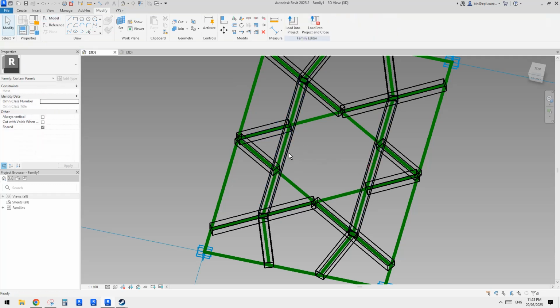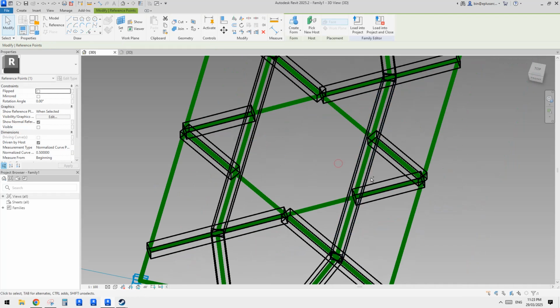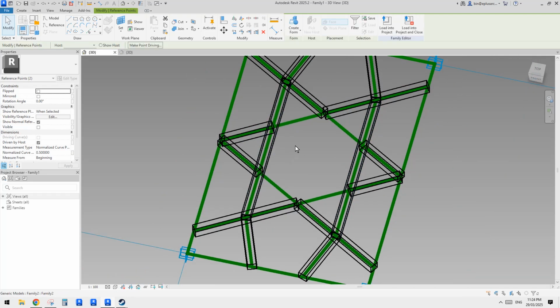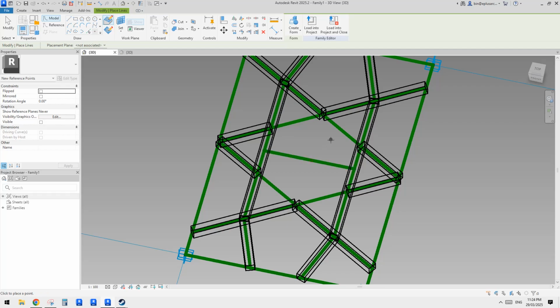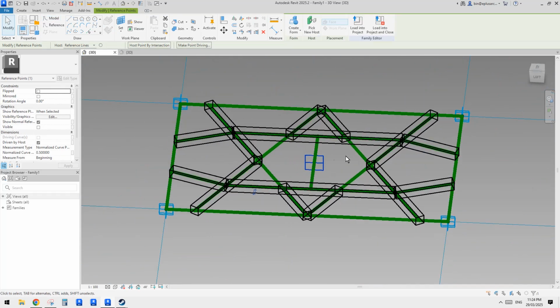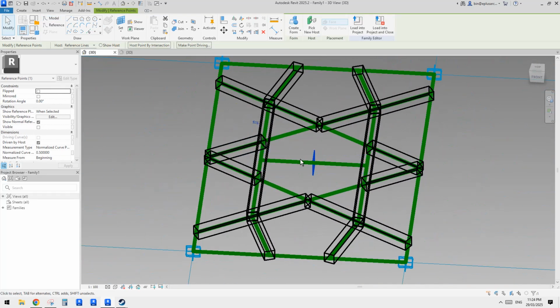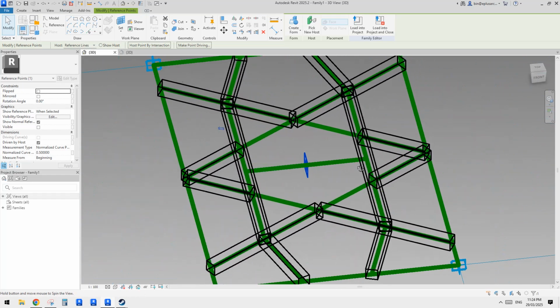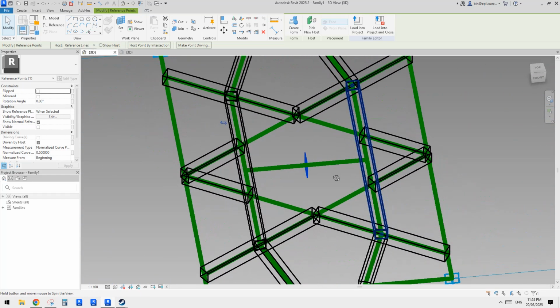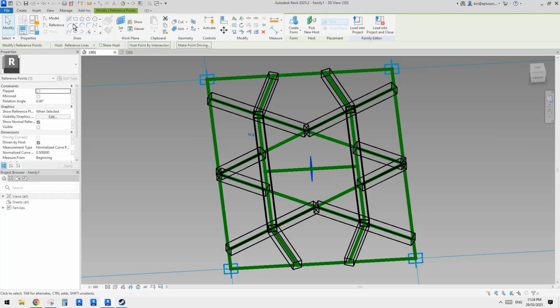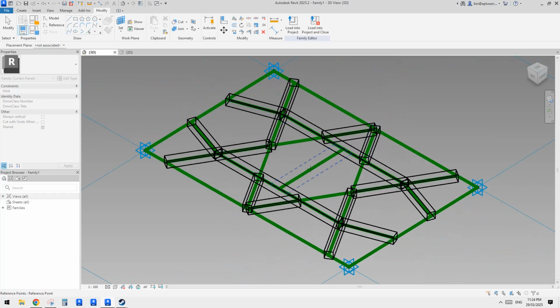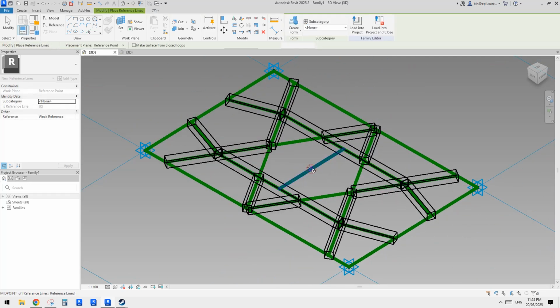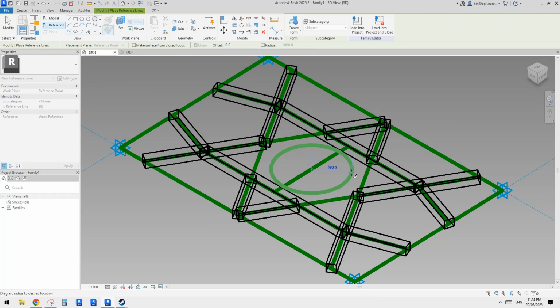Yeah, I should probably just do a line, but that's fine. Two points, and use splice rule points, make a reference line, place a midpoint on this. So now we have this point, so we can place a circle here, I think. Yeah, let's try this. So it'll be a circle reference, circle, draw work plane, set work plane, tab, until you see it's a horizontal work plane on this point.